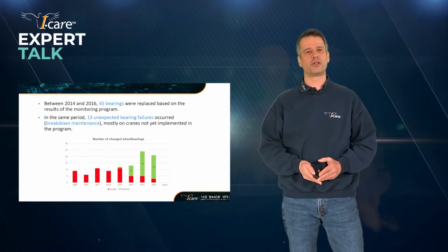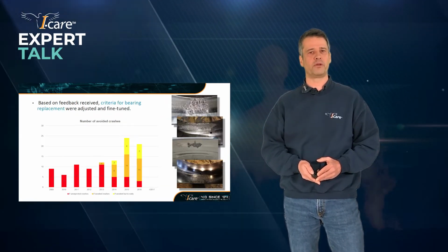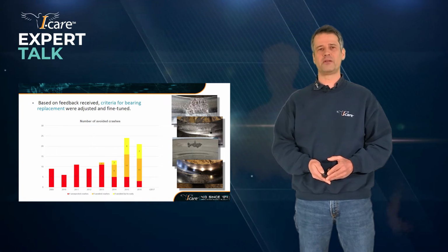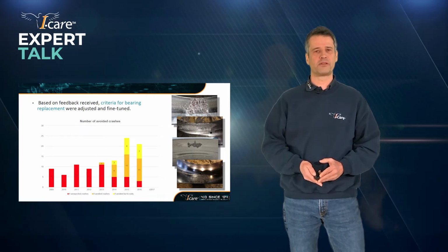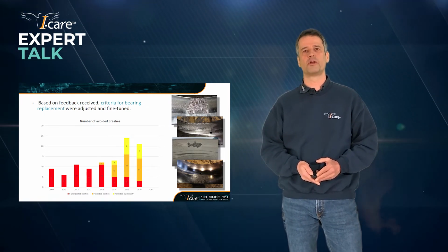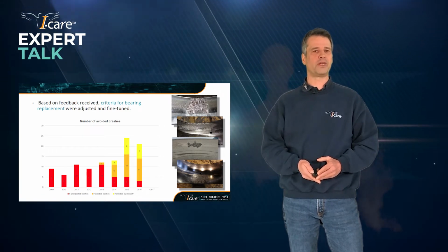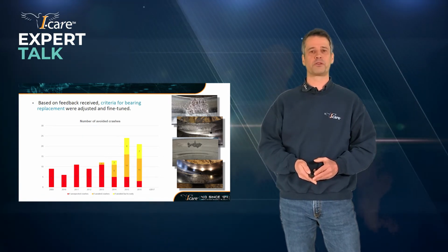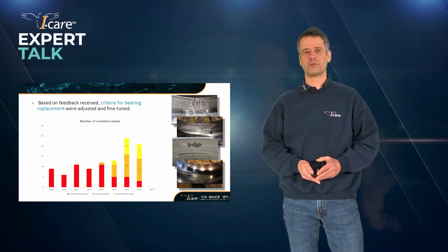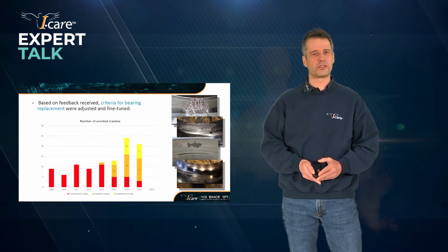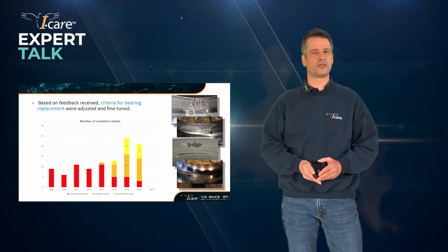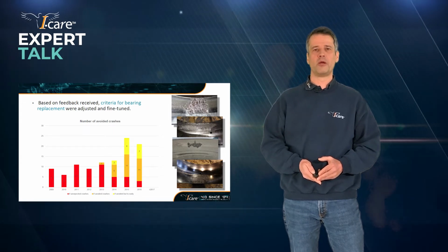Well, we actually saw that out of the 45 bearings that we replaced, approximately 30 displayed severe defects, like the ones shown on the picture on the right side, where we can really say that the replacement of the bearing was really justified. On approximately 15 or 16 bearings, we actually saw that the defect was visible, but